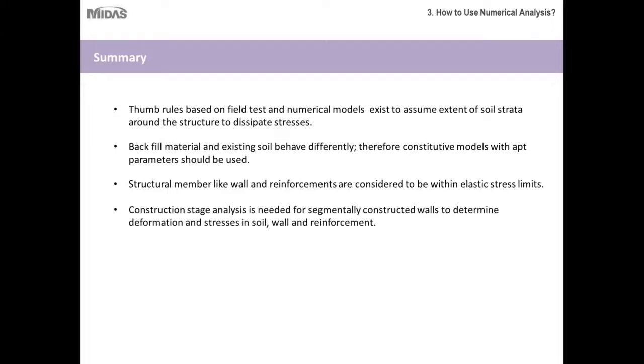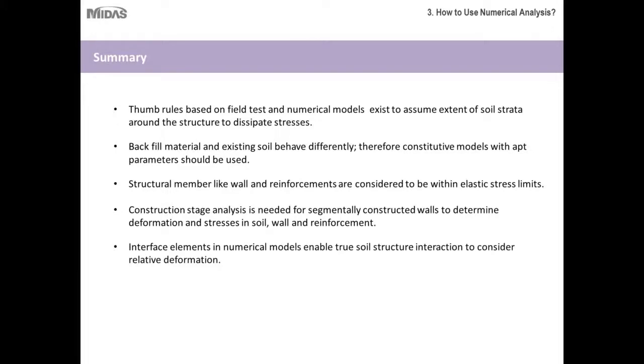The structural members like the wall with its foundation and reinforcement are considered to be within their elastic stress limits. The construction stage analysis is needed for segmentally constructed walls to determine the deformation and stresses in soil, wall, and reinforcement.